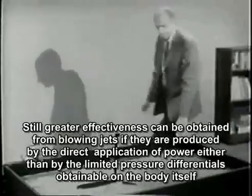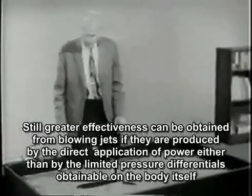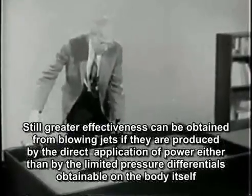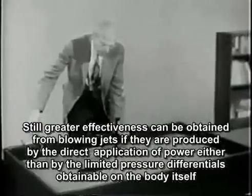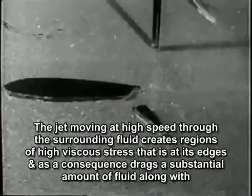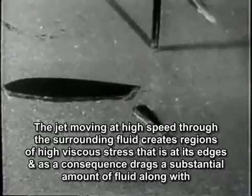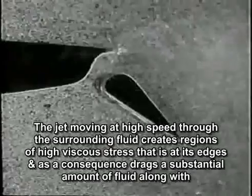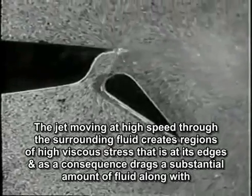Still greater effectiveness can be obtained from blowing jets if they are produced by the direct application of power rather than by the limited differentials available on the body itself. The jet, moving at high speed through the surrounding fluid, creates regions of high viscous stress at its edges, and as a consequence, drags substantial amounts of fluid along with it.